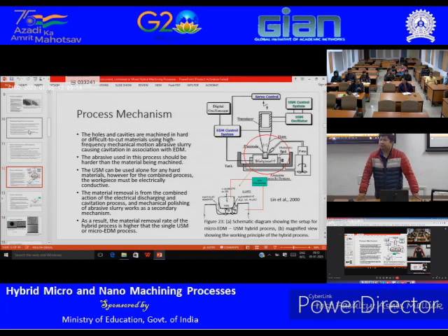So usually you are recirculating all the time, right? When you are recirculating, you are separating the debris and keeping the abrasives. Abrasive is non-conductive in most cases, and based on which material you are machining, the debris can be conductive or non-conductive. But again, particle size is also another thing. If your debris particle is much smaller than the abrasive particle, you can easily filter those out and recirculate those abrasive particles. So there are ways you can actually control that.